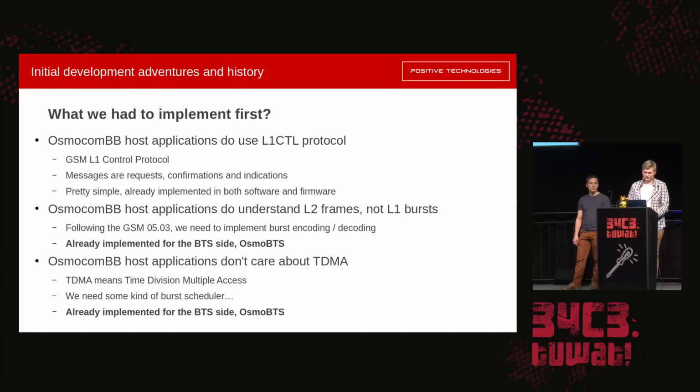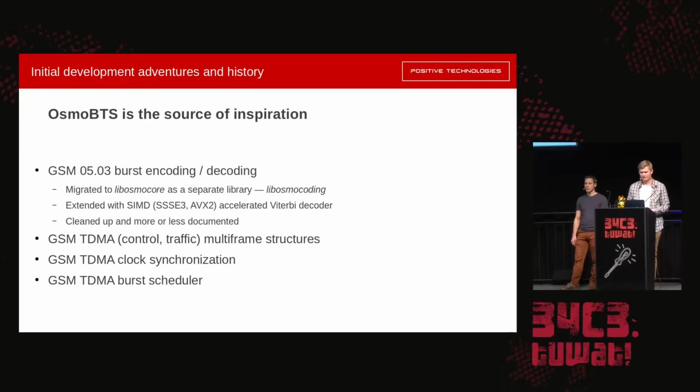Another problem is that host applications don't care about time division multiple access, and this is one of the basic technologies in GSM. So we need to implement some kind of TDMA scheduler here. And Osmo BTS became our source of inspiration because both things are already implemented there.